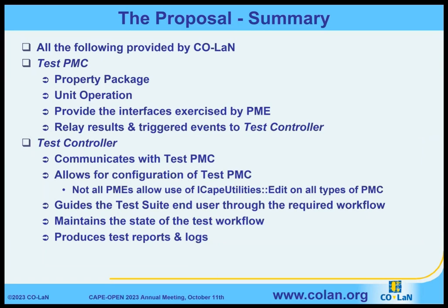So, just to summarise, CO-LaN will provide the test PMCs: property package, unit operation. That provides the interfaces that need to be exercised and tested from within the PME. So you're testing all the interfaces implemented in the PME, and it will relay the results back to the test controller, and any information about triggered events will be relayed back. The test controller obviously communicates with the test PMC, and it allows the configuration of the test PMC. Those two things are done from the test controller. So it will guide the end user through the workflow, maintain the test, and produce the test reports and logs. So that's just a summary of what I've just said.